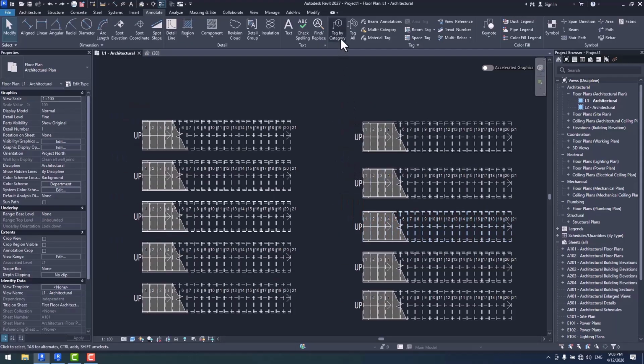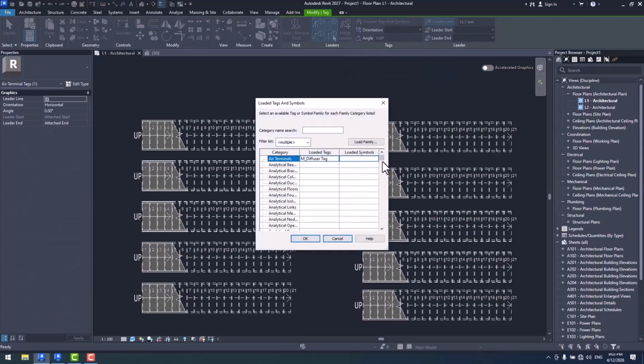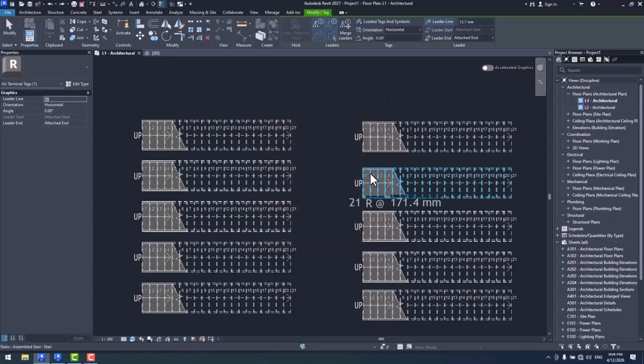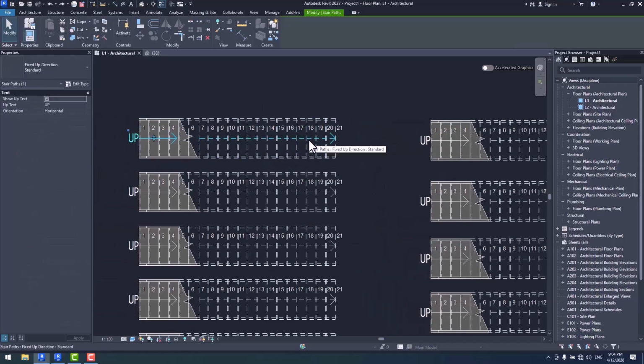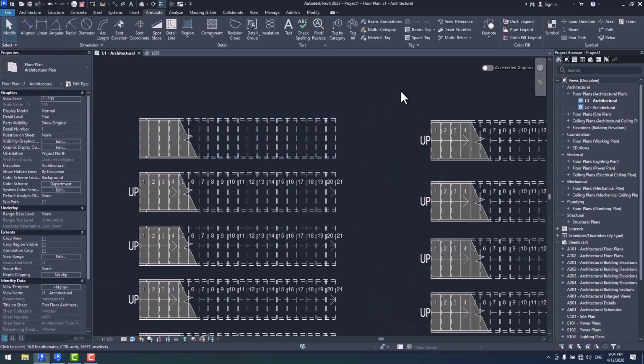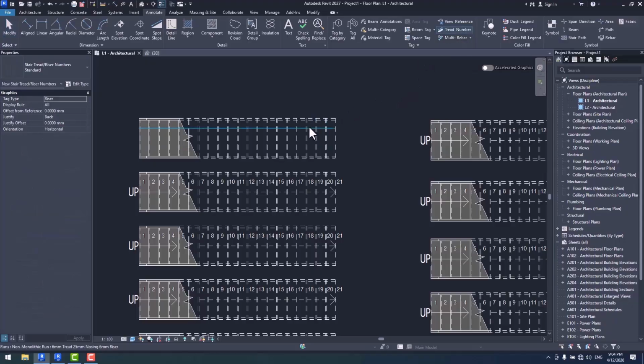Now, question, guys: do we also have this ability within Tag by Category or not? Well, no, we don't. And honestly, we don't really have to. We don't need it. We shouldn't even think about this, guys. We basically have Tag All because we want to work as fast as possible. We want to set the required tags on the items as fast as possible. We shouldn't think about using Tag by Category for such items, because it'll take a long time for the process to be done. Now we can just easily use Tag All, and it is very simple to work with.